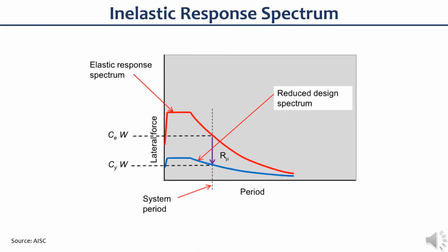One of the fundamental concepts we need to understand is the inelastic response spectrum. As you can see in this slide, the elastic response spectrum is reduced by the redundancy factor R, in which the values depend on the level of detailing. We have special, intermediate, and ordinary frame.